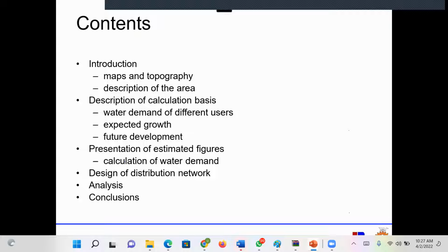The idea is that you need to reduce pumping costs. As an engineer, your work is not only about providing services to people, but you must provide it within a cost model. You can't build a house of 20 million for 100 million and you say you're a good engineer. So water supply systems are always done based on gravity. That's why in your houses, you have an elevated tank, so that as soon as you turn on your tap, the water just comes out.